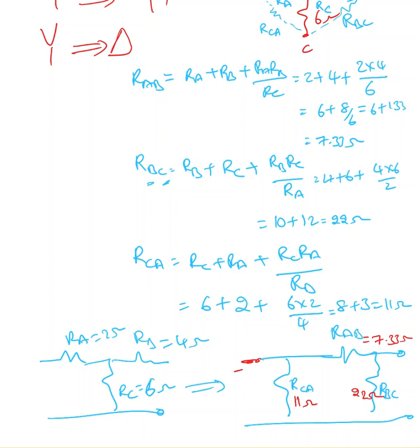So my network is going to be, this is V1, I1, this is I2 and V2. As long as a circuit is a reciprocal network, I can represent it using the T model. This is the T model. Now once I know the T model, I can convert it into the pi model.